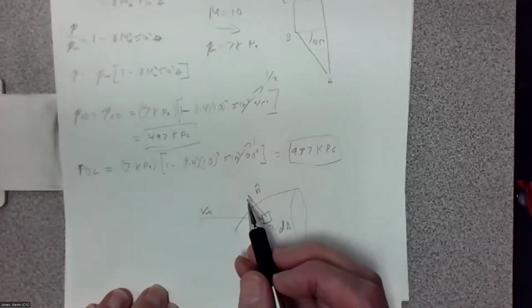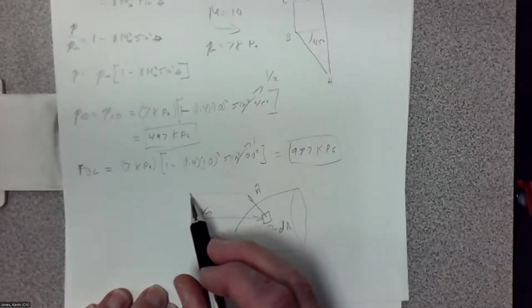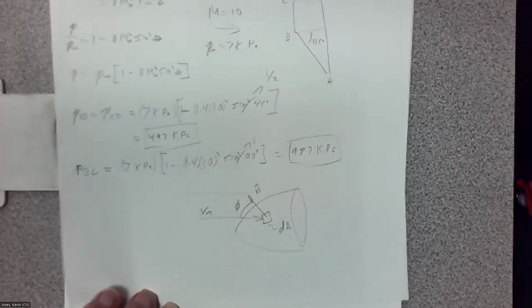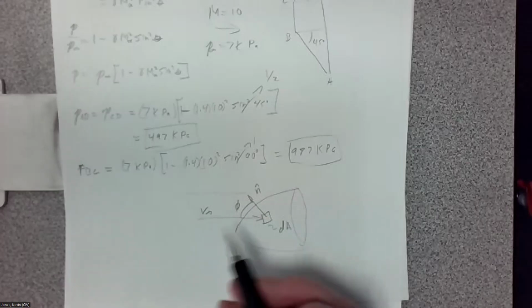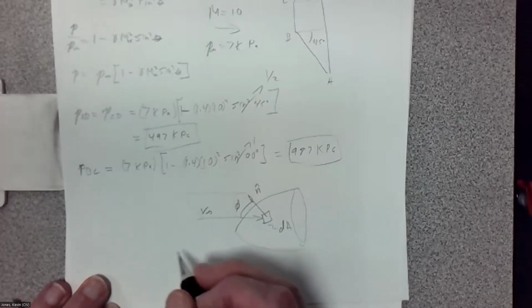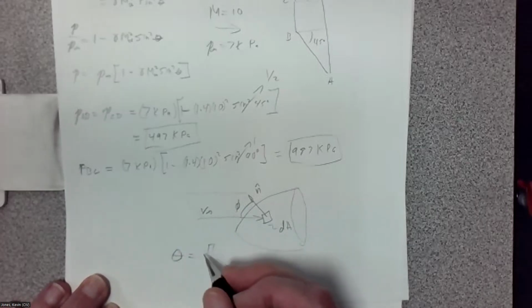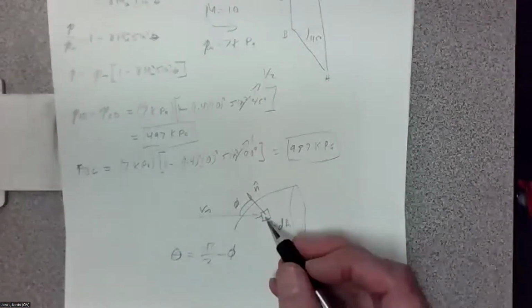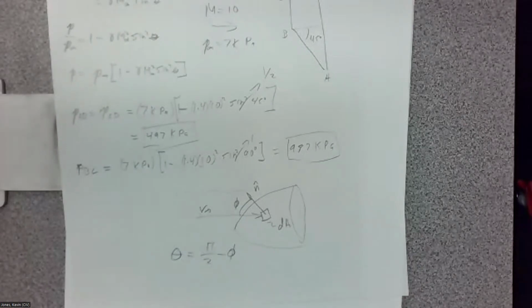And then what you'd want to do is make a plane between these two and measure this angle here, let's call it phi, between the free stream velocity and the normal. And then the theta that you want to use would be pi over 2 minus phi. The trick is in doing all that geometry. When you take the airfoil and move it, you could do it in SolidWorks actually. If you're good with planes and vectors inside of SolidWorks, you can have it do that for you.